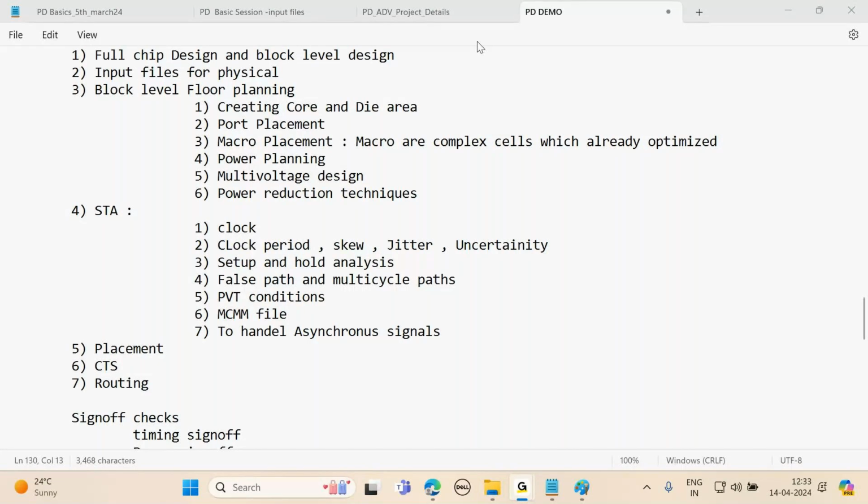There are hundreds of commands in physical design. So we use a somewhat less complex design, with 50,000 cells and 40 macros. I cannot bring a design with 2 or 3 lakh cells because the runtime is huge. Even here, a command like place_opt takes 1 hour to run.